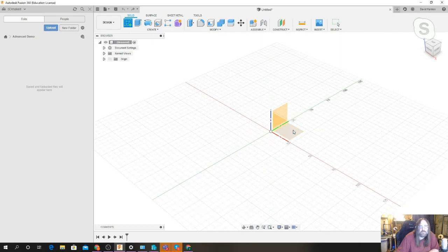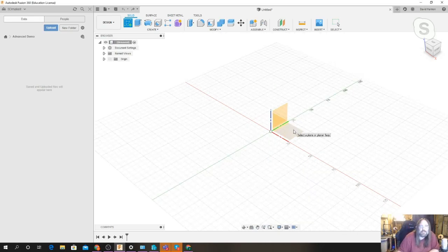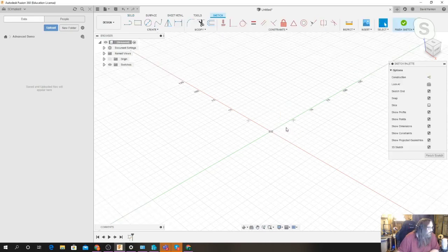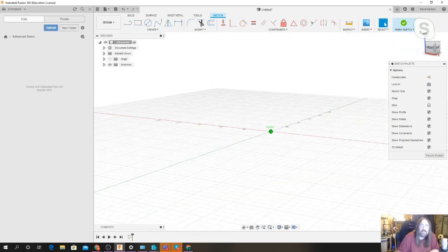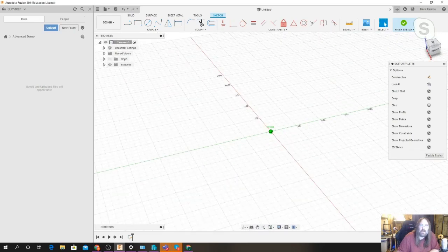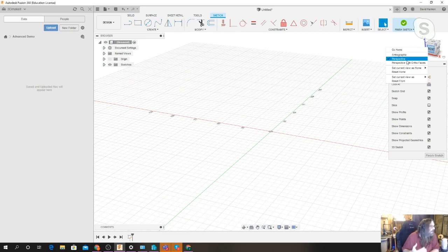So in Fusion, you should be able to hover over the very bottom construction plane, and that should put that grid path even with your screen. So it should kind of be flat across, and we just click it. Once you click it, we've selected our construction plane. Now, on the side here is the orbit tool. It's very similar to Builder and Tinkercad. They both have orbit tools. You can enter and leave certain display views if you want by right-clicking, and you could go to orthographic view or perspective view. Now the difference between the two is actually your perspective of the object.